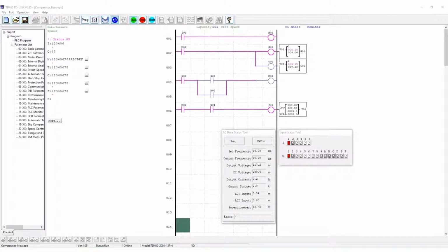G2 will turn on M2 and latch the G2 contact. The VFD will operate at 60 Hz until the tank level is pumped down to 4 volts. When the level drops below 4 volts, G1 turns off and stops the power flow in rung 6. This turns off the motor until the tank level reaches 4 volts again to start the motor at 30 Hz.